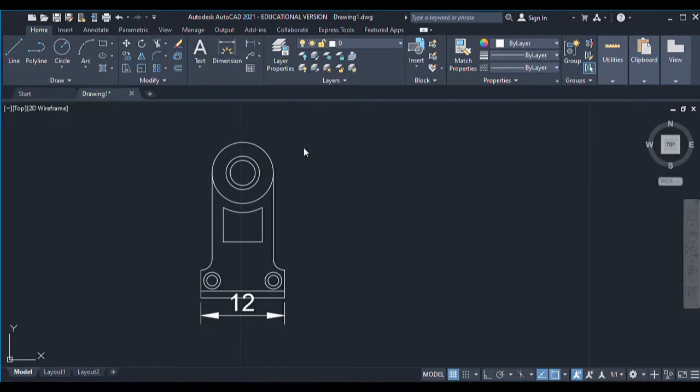And then you have all these things here. You can choose the style you want from here, but I'll go to manage dimension styles. Okay, so something will come on the screen, then you go to modify. Okay, so from here, go to fit, and I want to change this one to 0 point, close. So you can see that my dimension now looks more beautiful.